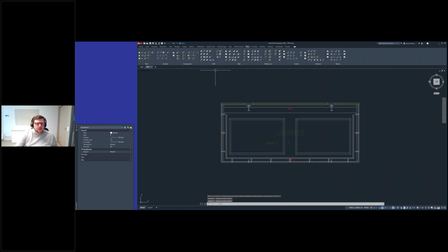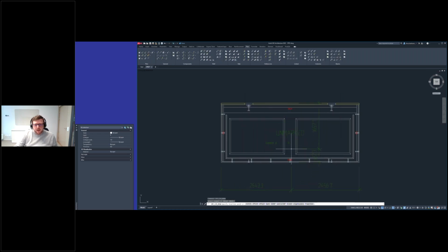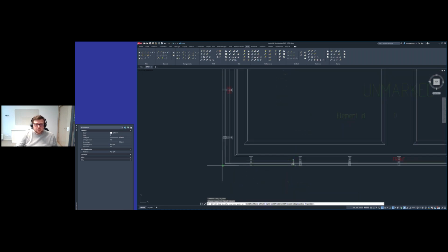And then the last thing, I will add another custom material, and it's going to be this one on top. So here it's manual. You can have the jigs so that you see the dimensions, but you also have some options here. I would like to add this 200 millimeters in Y and X direction from the corner. So I use my offset here and say 200, and then offset Y 200, and then I click this corner.